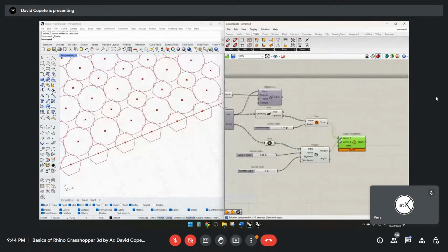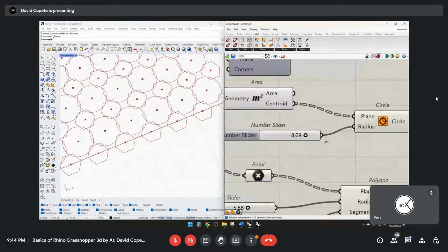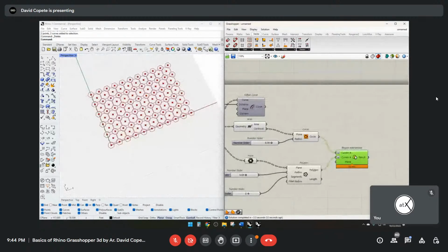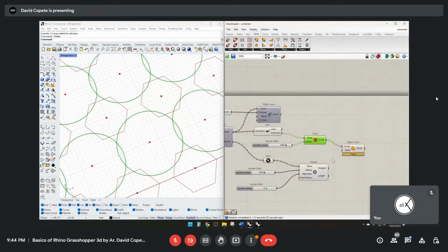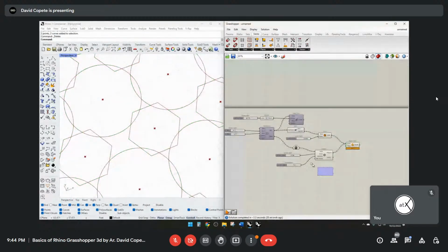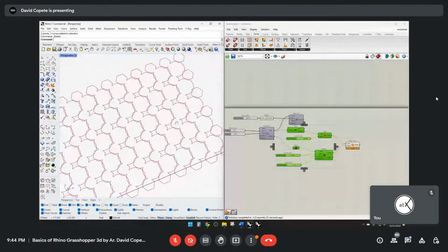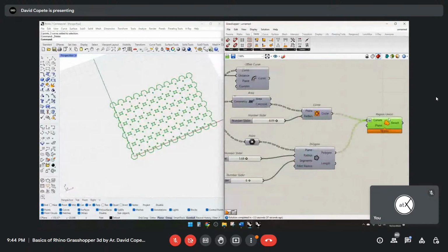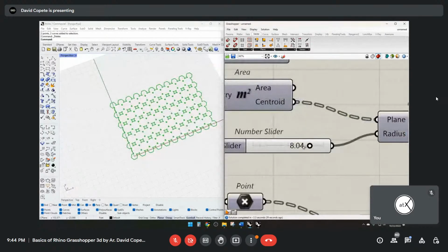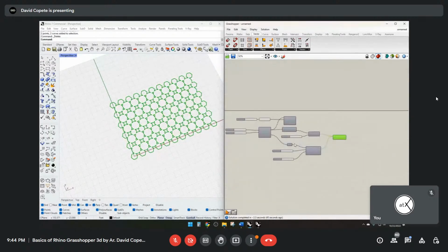Let's see if we can change the size. What I was trying to do here is you can take geometry like this where they overlap. Let's see if region union. So we'll take this and this, and where they overlap, that is what can be extracted. So let me show you here. So we can take the difference, or them being joined together, kind of like this, two different, and create custom patterns and stuff like that by just overlapping geometry.